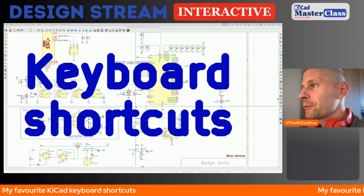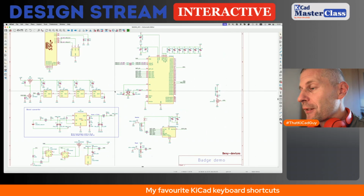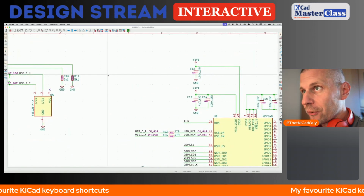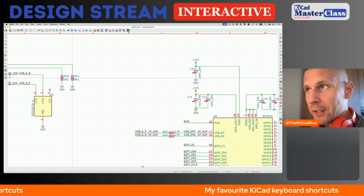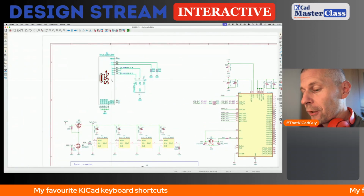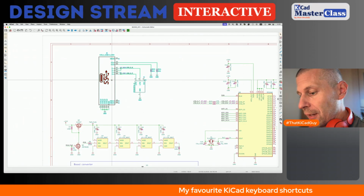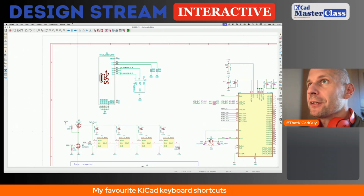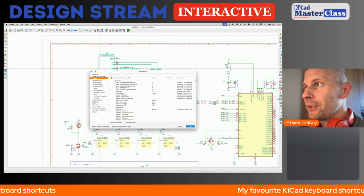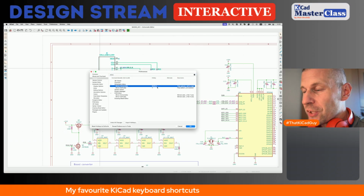So let's start. I will start from the schematic, and I think the first most useful shortcut is horizontal mirroring. Let's say you want to mirror a symbol or the entire block. The standard keyboard shortcut is X, but I redefined it. I will show you where. You go to KiCad settings, hotkeys. There is mirror horizontally. I redefined it to Shift plus X.